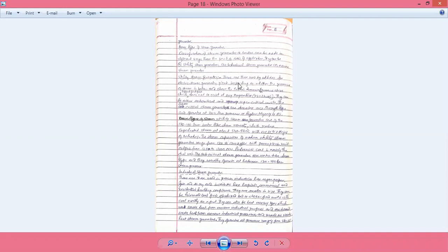The critical pressure of steam is around 220 to 221 bars. At the critical pressure, we don't have any mixture of steam or vapor. Due to the different portions of the TS diagram, you have either the liquid state or the gaseous state. This vapor is not usable in the liquid state, so we mostly use it above the critical temperature.